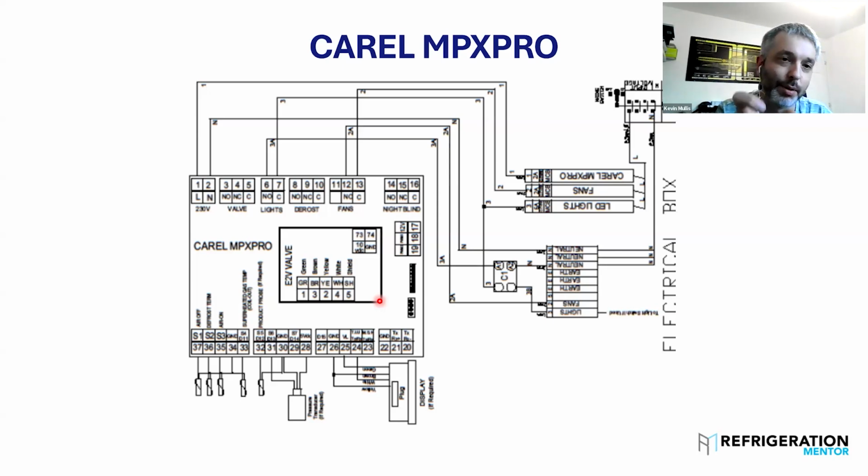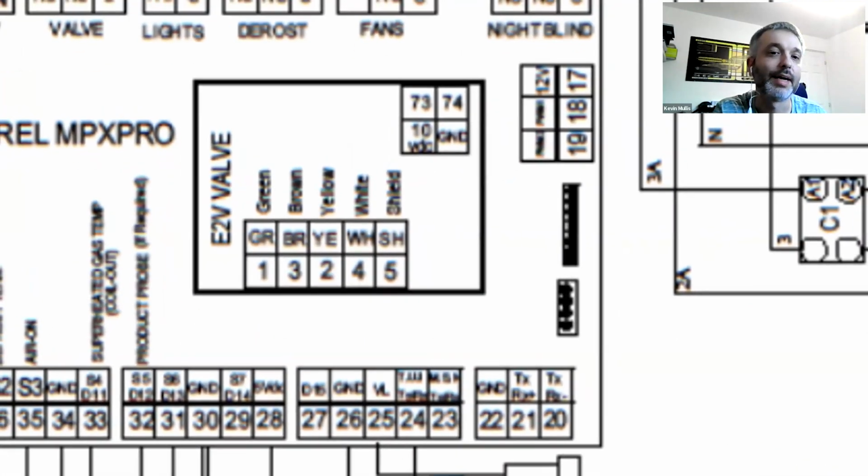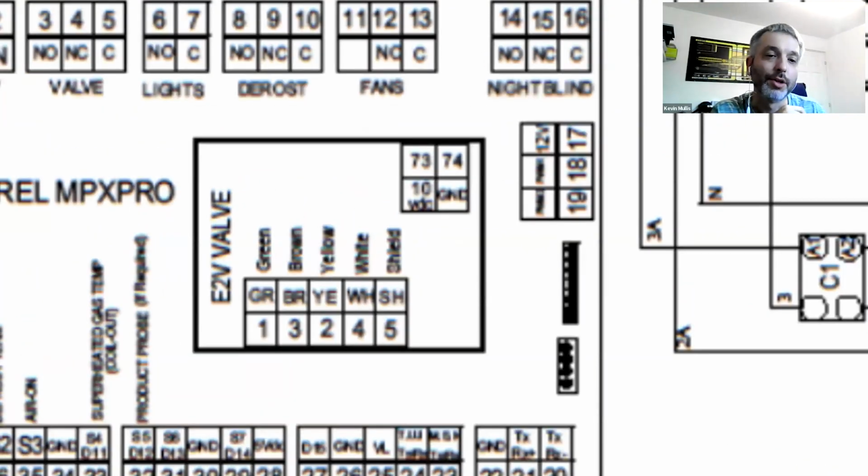If you disturb that valve plug and it's driving, you're going to need to reboot the controller to put the valve back to where it needs to be, or wind the valve shut with a magnet. It's also sensitive to how those are wired up. So on a stepper valve, you've got two coils in the valve stator, 1 and 3 and 2 and 4 on the terminals there. And you can check if that's working with resistance. If you unplug the valve from the board, you'll have continuity and a given resistance on 1 and 3, and you'll have continuity with a given resistance on 2 and 4.